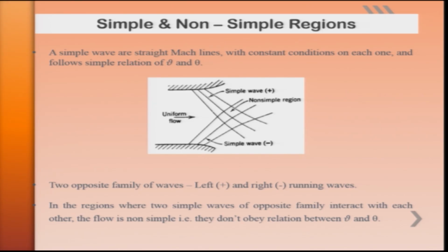If we talk about that from the Mach wave perspective, and we just said that Mach waves and Mach lines are real in nature, where however the Mach lines are where the changes are finite but very small. These are replaced with characteristic lines, and these characteristic lines in the two dimensional picture as shown here can be given as per their direction.